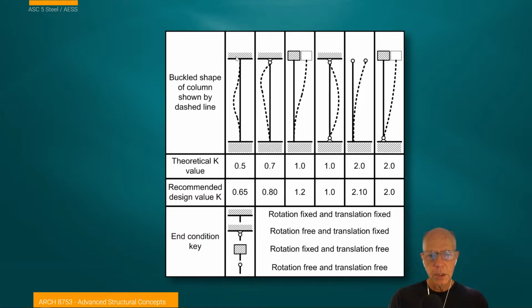That means that in the case of this column here, you're seeing that very small buckling region, as opposed to one over here, which has a very large buckling region. And that's because this rigid connection up at the top and bottom is working to help stabilize or reduce that buckling. So this column, by the nature of the way the ends are fixed, is stronger.